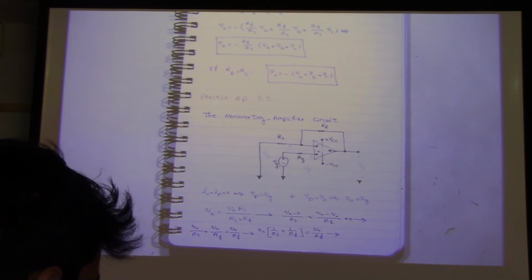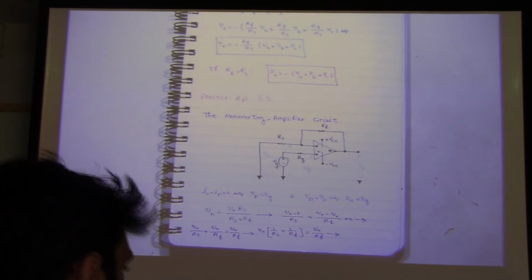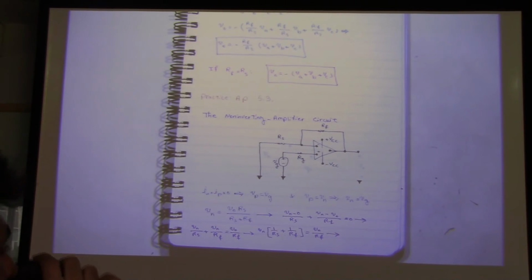Okay, I explained that usually when we use an operational amplifier, we have power supplies, positive and negative, right? This value usually doesn't exceed 20 volts. In practice, you have power supplies. When you use this IC, you should not go more than 20 volts, okay? And for the gain of amplifiers, usually you should not go less than 10,000.